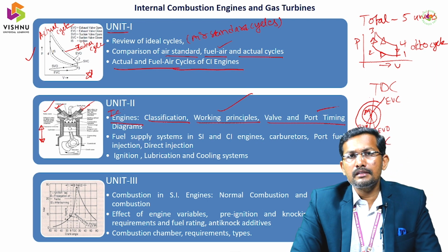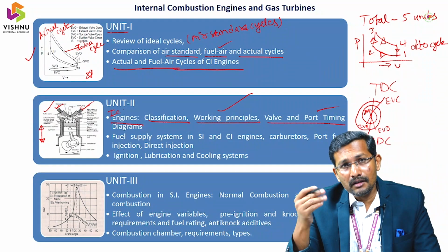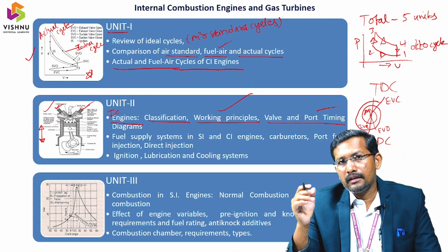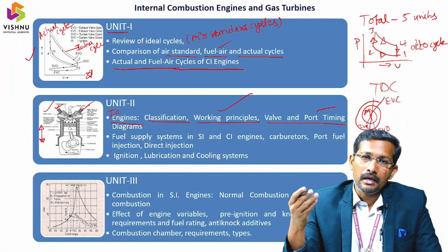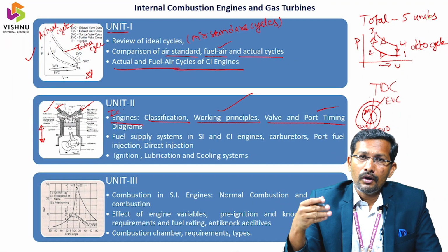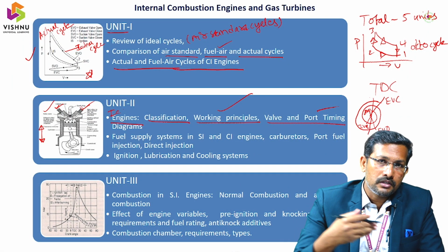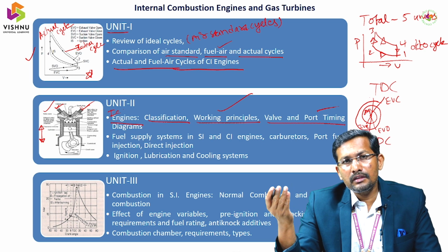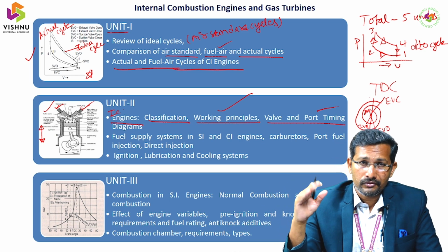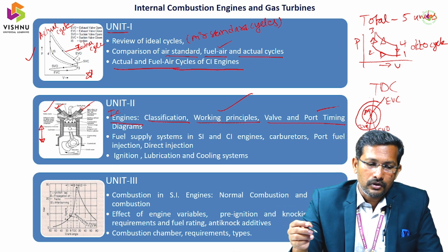The port timing diagram is for the case where instead of valves, some ports are there. But the same story is applicable there also. How the valves are opening and closing with reference to piston position, in the same manner we have to see how the ports are opening and closing with reference to piston position. That is the port timing diagram.